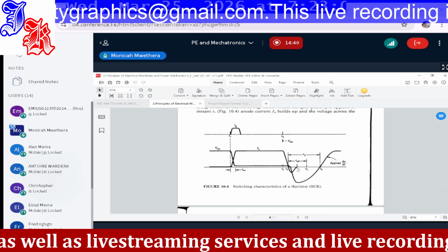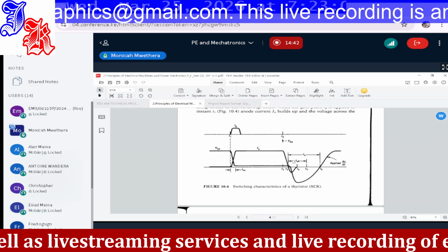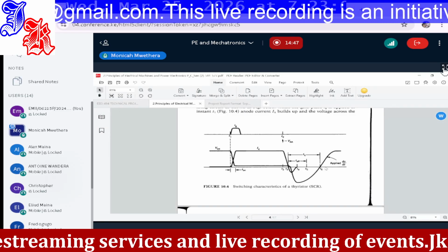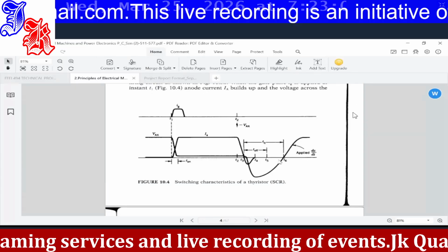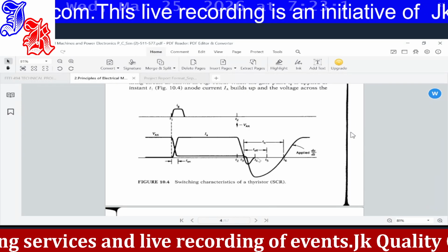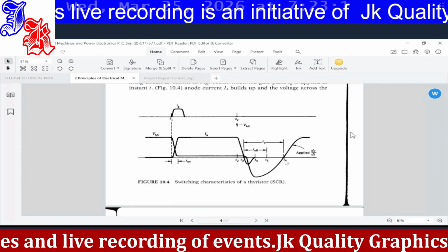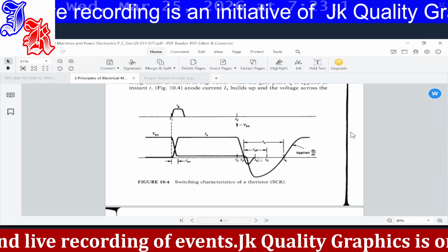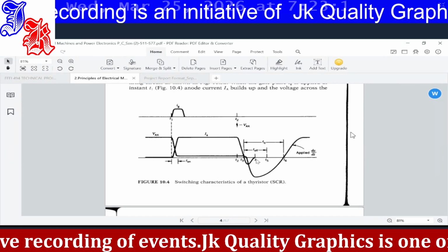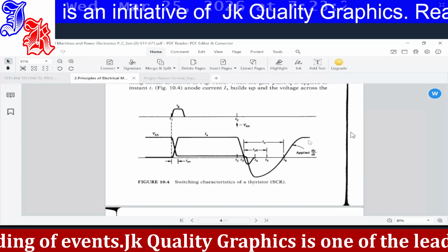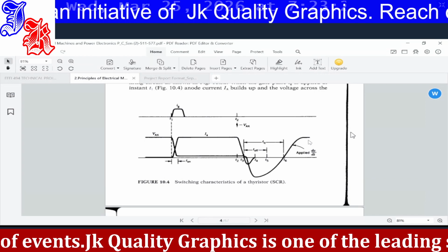This is because of the forward voltage that can happen. So the T off can be prolonged. So we'll see what is T4, T5, and T6 that is turning off. But mostly you can see the thyristor is not conducting at T4 and also at T6. But the moment we apply another voltage after the blocking time of the thyristor, we can start again having conduction happening.